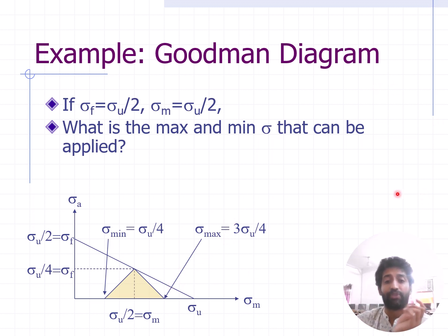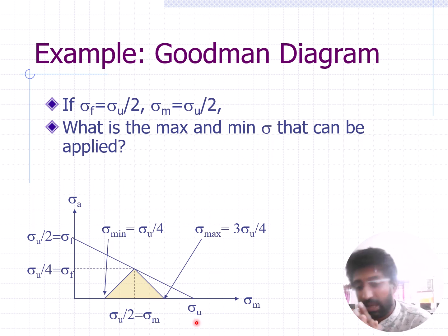It is used where fatigue is necessary, but controlled fatigue is necessary because we are talking about ultimate load. But here comes one point. If you want complete safety, you will not go for the ultimate one. You go for your yield stress, where it is under your elastic zone. Now it is explained by the Soderberg diagram. But in the Goodman diagram, we actually deal with the ultimate loads to get whether there is a chance to break or